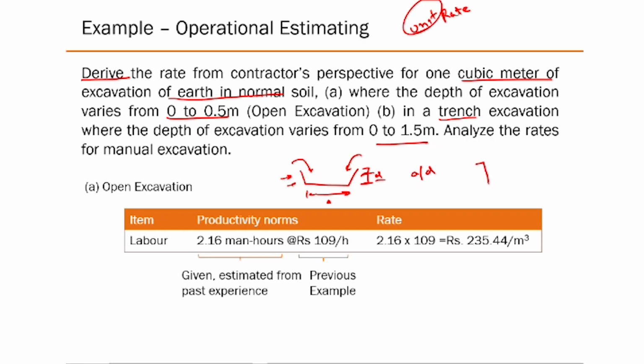So trench-based excavation usually requires some sort of profile. It's a little more complex profile than a normal excavation. Now you may need to put some sort of soil stabilization material. Either you put a slurry or something, or you might even put some sort of formwork here, or anchor bolts and things like that, to keep the soil from caving. Right? So this is slightly more complicated.